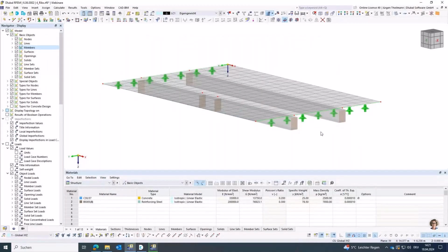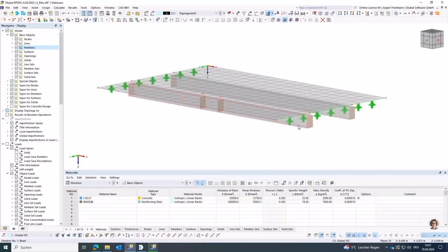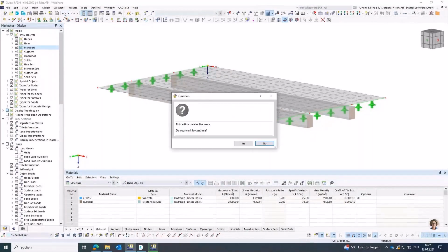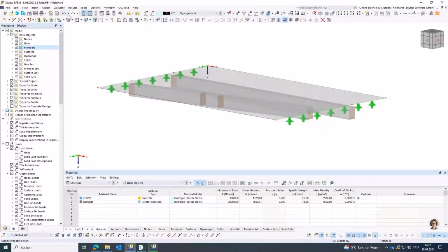Okay, that would be one solution. However, when you do this, you lose the integration width to this downstand beam when you don't use it as a rib. So I undo my changes and say that's not a good solution. It's a solution, but there are better ones. I undo to the first